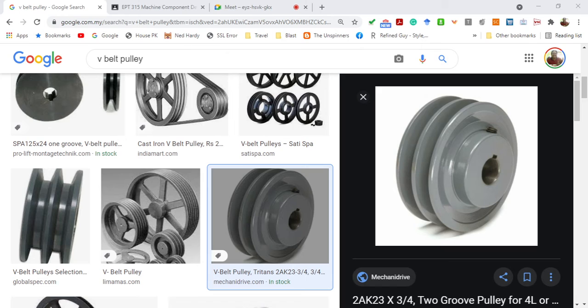Timing belts are made of rubberized fabric and steel wire, and have teeth that fit into grooves cut into the periphery of the sprocket. The timing belt does not stretch or slip, and consequently transmits power at a constant angular velocity ratio. The fact that the belt does not slip provides several advantages. One of these is that no initial tension is necessary, so the effective center distance may be used. Okay, timing belt.